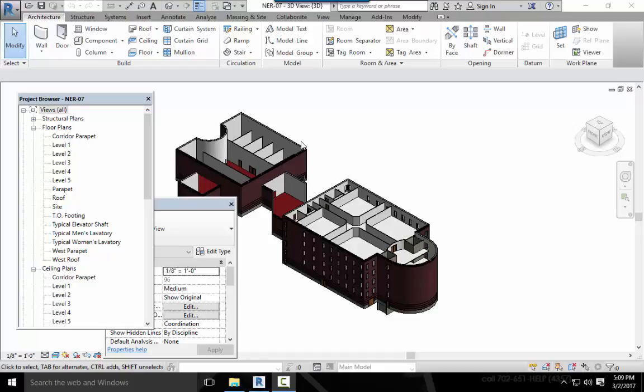All right. So we're going to place a couple different types of roofs using the place by footprint: a flat roof, a gabled roof, and a hip roof. Flat roofs by footprint. To begin, open the file you've been using, or chapter 7. I again recommend you start with the new file every time you start the chapter. The objective of this procedure is to create a flat roof by outlining the building's geometry in the plan. Follow these steps. In the project browser, double-click on the roof view in the floor plan section.